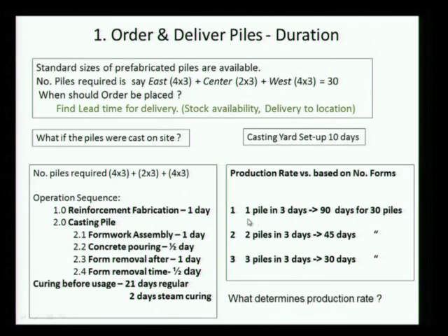So here, if you take a look, I have 1 day for reinforcement fabrication, formwork assembly, and concrete pouring, so here you have 2.5 days. I remove the form after 1 day. So here 1, 2, 3, 4 days. After 4 days I can reuse the form.